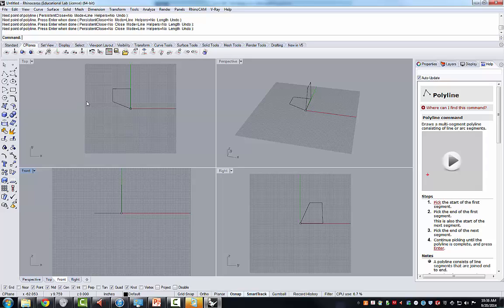You will find the need to manage construction planes and to work on construction planes that might exist in 3-dimensional space. Let's say I wanted to make a construction plane from one edge of this to the other in some very odd orientation in order to draw something that would later contribute to my model in an orientation that is not one of the cardinal X, Y, Z axes. You can certainly do that using construction plane adjustments here.